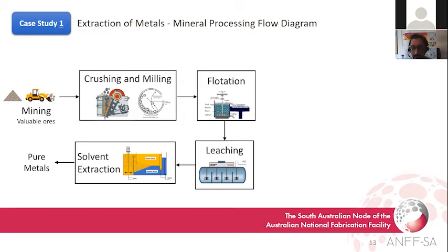And turbulence exists in the slurry phase and conditions change quite rapidly. So the key is to collect a small volume of fluid free of particulate matter from a stream with a high solid loading. This can be difficult at a point in a process line with high solid loading, which can damage or even break and block the sensor array.